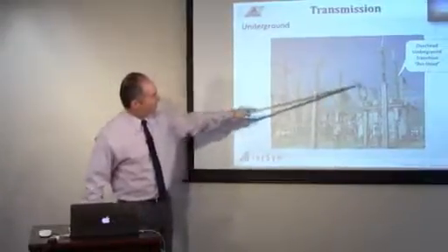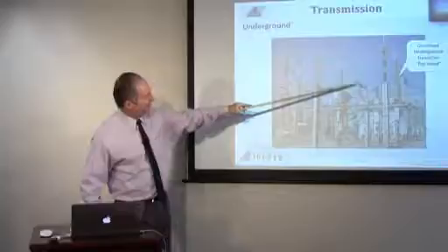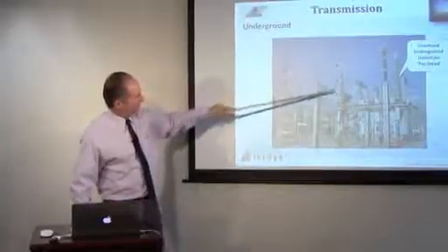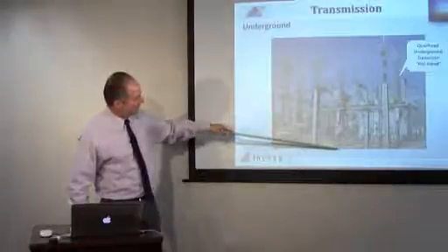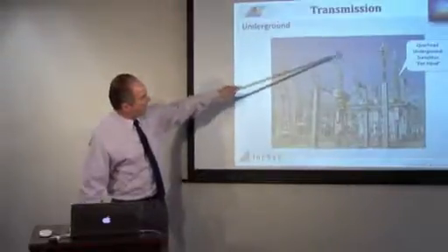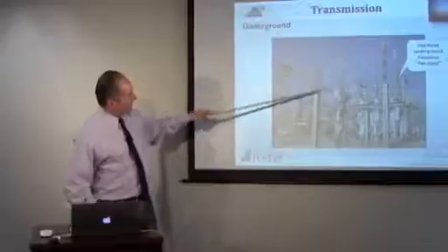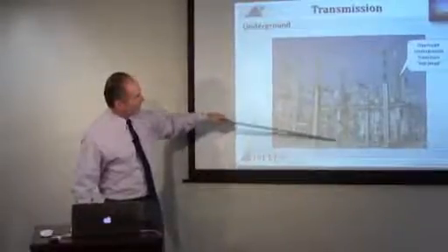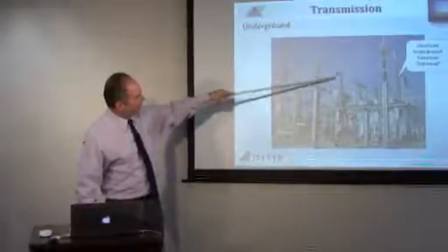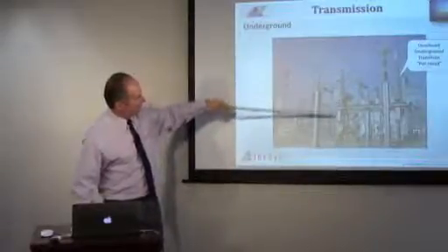Here's a disconnect switch. And then after the disconnect switch, you're coming into the pothead, which actually has an underground transmission cable going into steel conduit. And then over here you have a lightning arrestor to protect it. The lightning arrestor helps clamp voltage so you don't destroy any of the underground cable. So this is the pothead that's going overhead to underground.